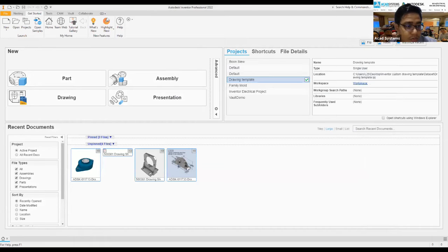All right. So for this case, I'm going to the C drive, and that will be in Users, Public Documents, Autodesk, your Inventor version, Inventor 2022 for my case, and Edit Drawing and the Templates over here. So right now we have multiple templates. For my case, I'm using the English US templates. And if I want to get more details, I'm going to use templates from the Metric folder.